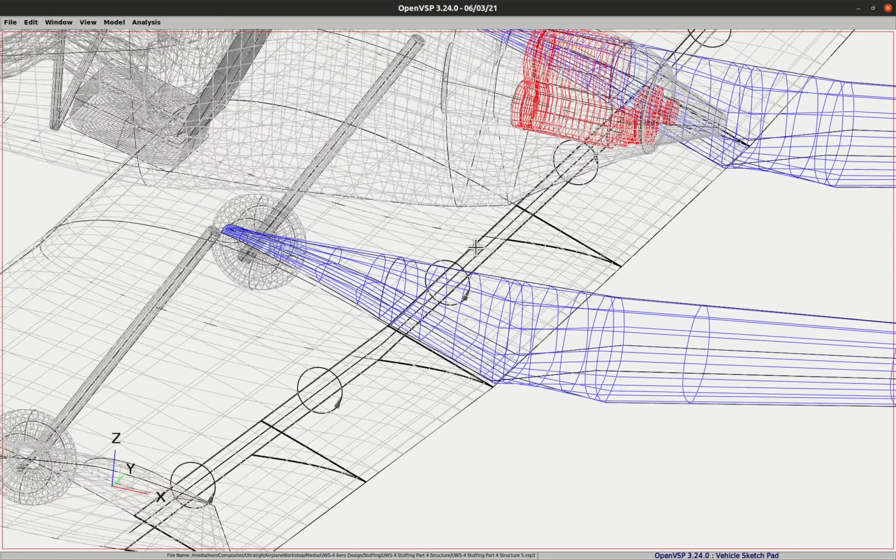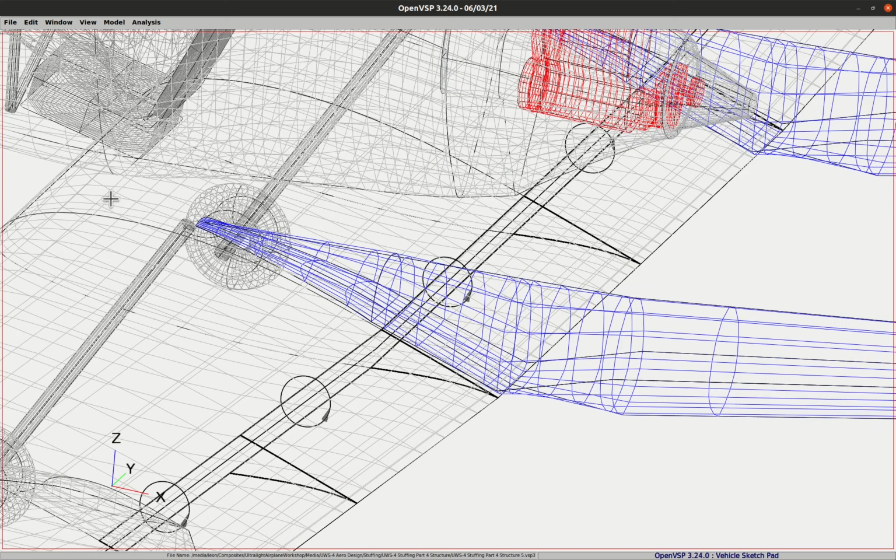I've got a little bit of an issue here. I want to have this wing keep its normal shape. I don't want to do any cutouts into this flap that's here. So this area right in here will act a little bit like a split flap where the flap is going to be underneath this boom. So right here and here are attachment points for the boom, attaching to the rear spar, and now it's going to have a single attachment up here where the main spar is.